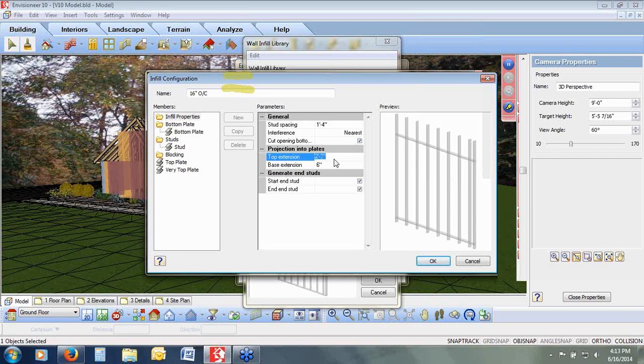Why is that helpful? Where do you see that being useful? Well, for our steel framers. We have a lot of end users that use the software in their steel framing. They wanted to project those studs into the top track and bottom track. Previously, it would stop you when it hit the bottom edge of the bottom plate or the top plate. Now you can project those steel studs to more accurately display the steel framing capabilities in the software.